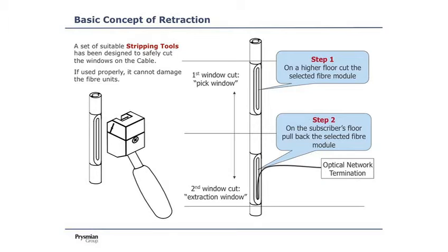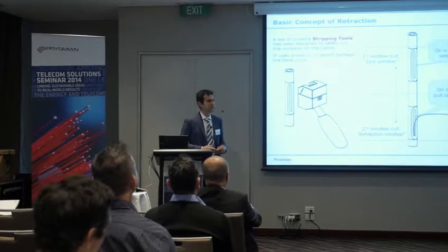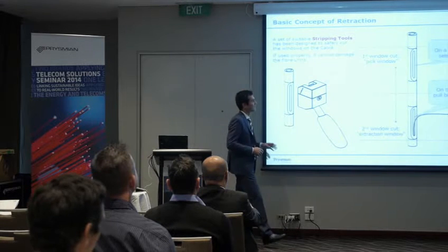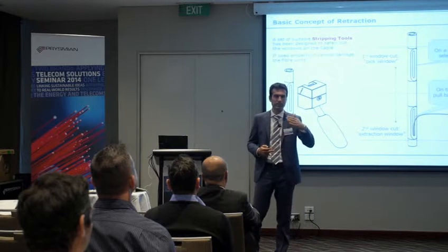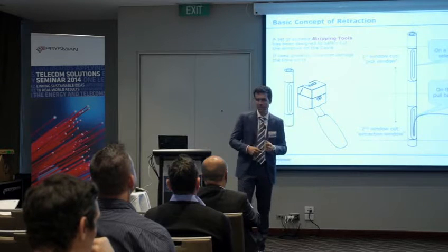This one is not a rocket science item, even though I have a patent on it, probably the only one in my life, because this is basically the potato peeler. It's the one you can use to peel the skin of the potatoes. A bit reinforced because the cable is a bit thicker in this case, but it's exactly the same kind of story. The important thing is that the blade, when it enters the cable, will be parallel to the fiber. Don't grip on them.